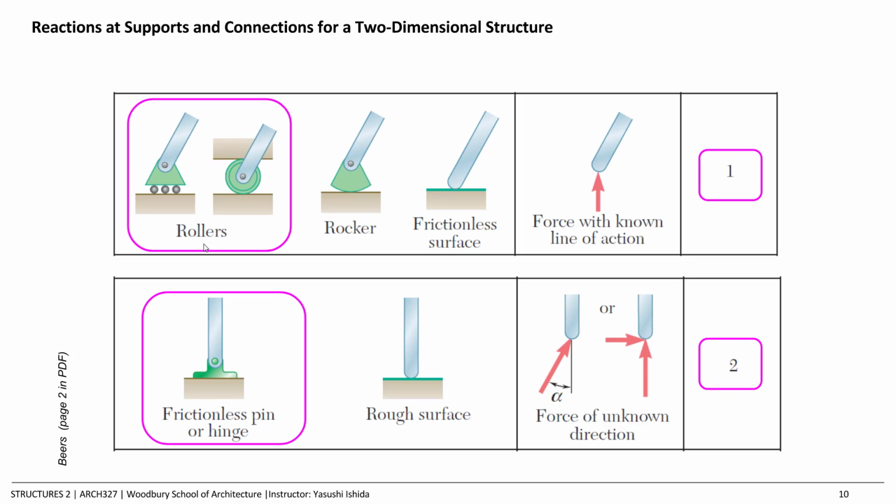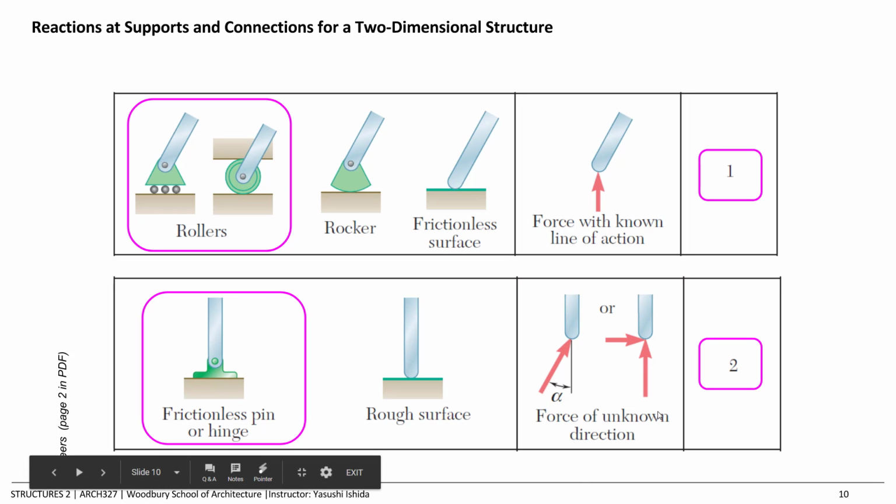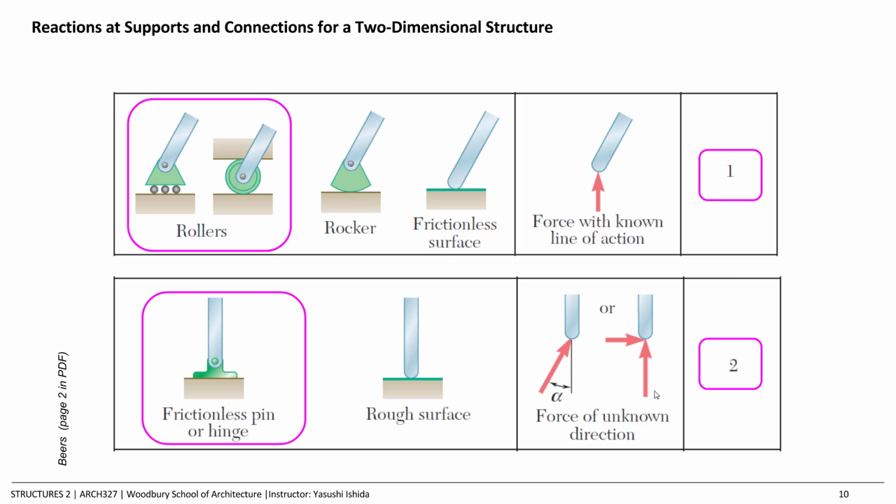The more intuitive way is, if I'm pushing it this way, the applied force is this way, and your reaction at the joint must be in this opposite diagonal direction. It looks like one reaction, but by convention we divide that diagonal reaction into horizontal and vertical components. The diagonal is actually resisting this force in the vertical and horizontal directions, and that's why it's defined to have two reactions.